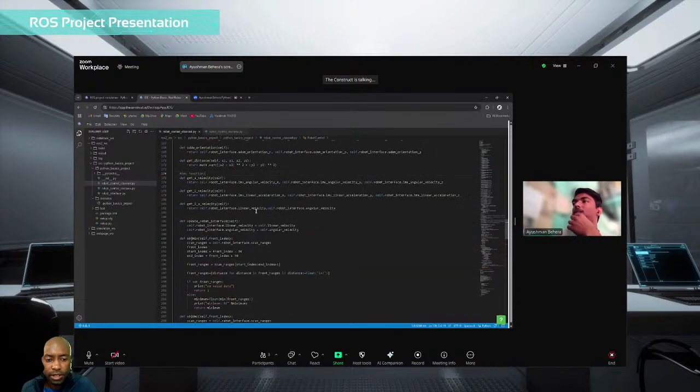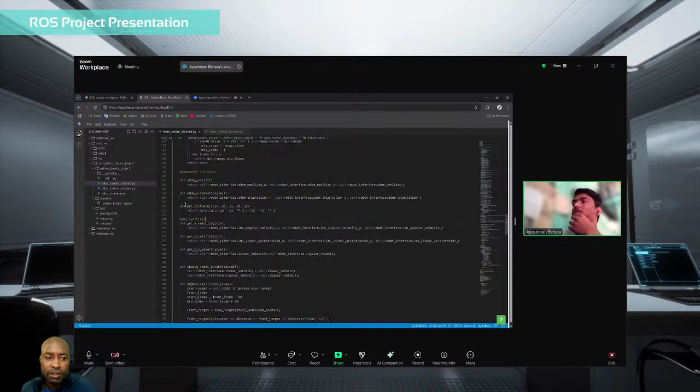So you would check, in your obstacle avoidance, your robot is going in a loop, is that right? If you use Euclidean distance as a metric to keep checking how far you've gone from the beginning point, how are you going to deal with the fact that at some point you'll be going back to the beginning? I think I will just define a threshold value. If I'm within that range of that point, I will just stop the robot at that point using the same function, the get distance.